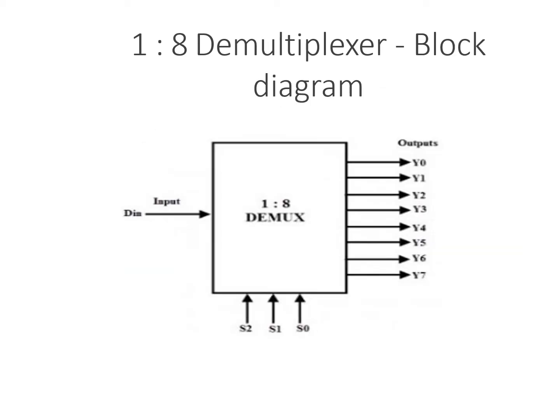Next comes our 1:8 demultiplexer. Now the enable is not actually shown, it is obviously understood, right? What is the data input here? The data input is not going to change anyway, only the number of output lines that we are going to connect is changing. Distribution of lines is changing. So 1 is the input and the output that I require is 8. 8 means 2 to the power of 3, in the sense 2 to the power of m. M is equal to 3. So we are choosing 3 select lines and the outputs are 8 lines.